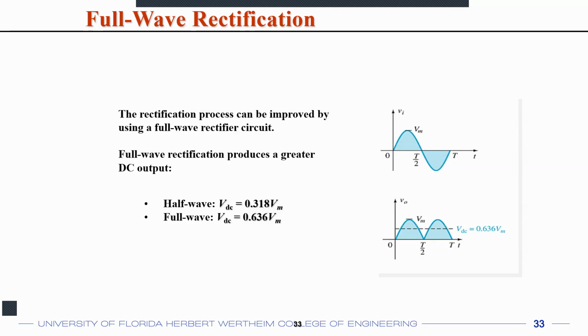The generator or the inverter creates an AC signal from DC, right? But if you want to create a DC signal from AC, let's say you're receiving some amount of power on your cell phone and you want to convert that to energy. You want to store that energy in a capacitor. Because you're receiving a sine wave, the average value is 0, right? But if you receive a sine wave and then half wave rectify it or full wave rectify it, then you'll get a non-zero DC voltage and you can store that DC voltage in a battery. So that's how, for example, wireless chargers work.